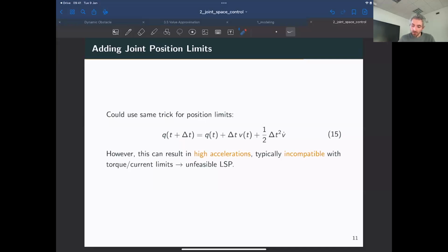So the reason is that this constraint is not looking enough into the future to be able to anticipate the problem of the joint position limits. And there are approaches that allow you to do this anticipatory behavior in advance, and include that inside this kind of least squares based optimization controller. But that would take me a little bit to explain, so I just point you to these publications in case you want to know more about how that is done.